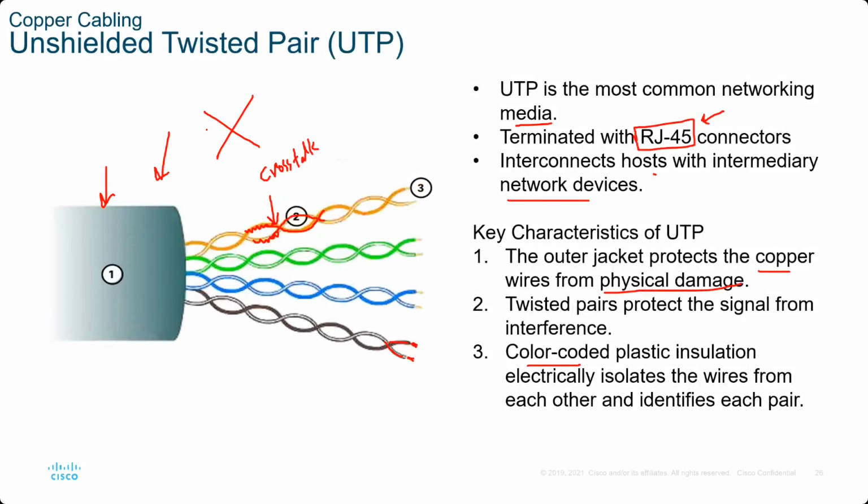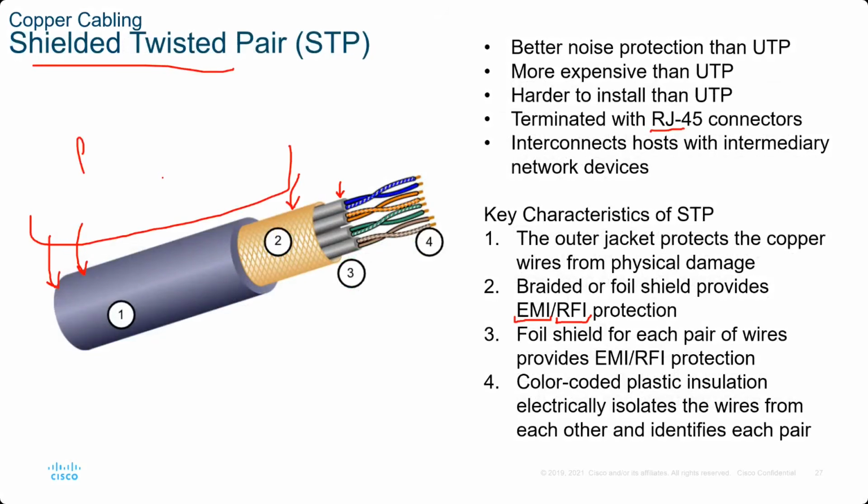You don't have strong electric wiring going on there, then you can use them. But if you fear that there is other electrical equipment going close by these cables, then use shielded twisted pair. That will give you better performance. That's the only difference.